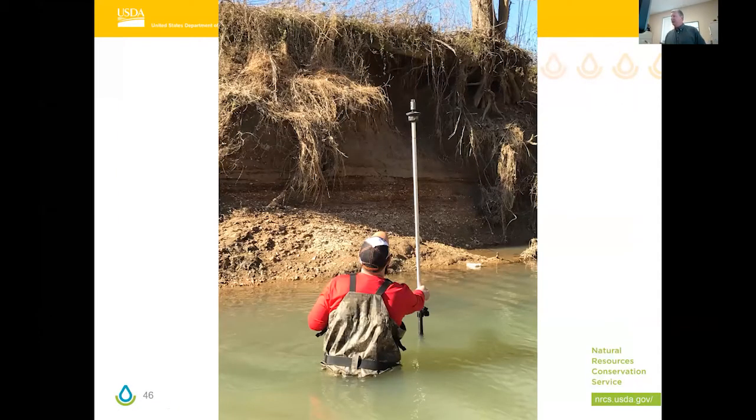So we always do a fairly extensive inventory, including engineering surveys, anytime that we have stream banks that we're working with. We'll take up and downstream cross sections. We'll look perhaps for a half a mile downstream. We look at historical imagery. We look at the plan form and how it's changed over time. We look at point bars. We try to determine the density of point bars to see how long they've been there. All these types of field techniques are actually used by us in designing the practice and considering what things we might do.